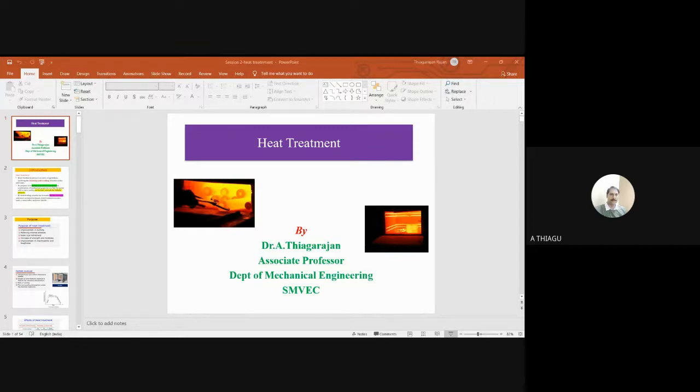So already we have suggested this. This is the information on how mechanical properties after the cooling process will be increased. Ultimately, I can say the temperature we have defined will increase the elongation. That is, ductility will be increased. As a result, toughness, that is impact energy, will be increased, and strength will be increased. So these are the three mechanical properties involved for annealing: impact energy, tensile and yield strength, and elongation.